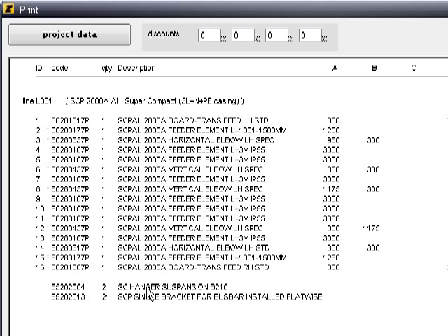this project. The hangers are automatically defined, verifying how many meters are installed in the horizontal layout, how many meters in vertical, and in particular for horizontal layout, the software understands how many meters in the edge position, how many meters in the flat position, and calculates the number of necessary brackets.